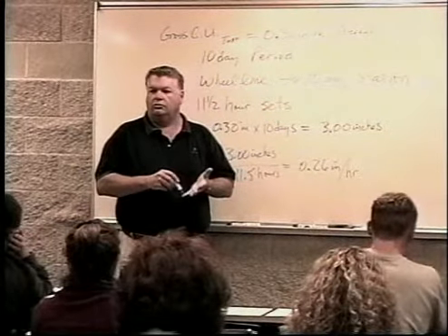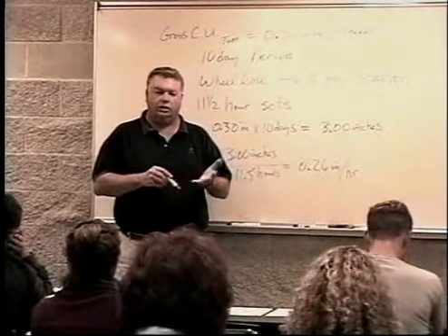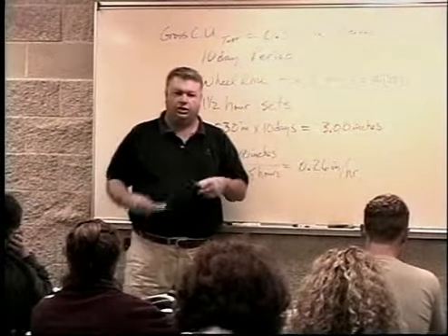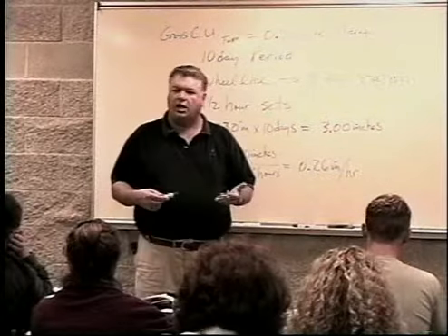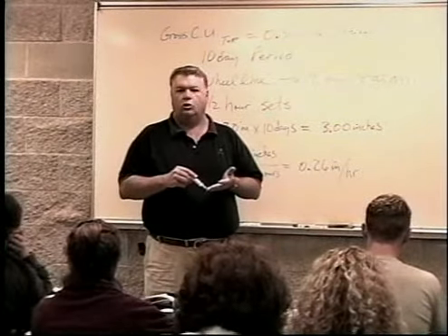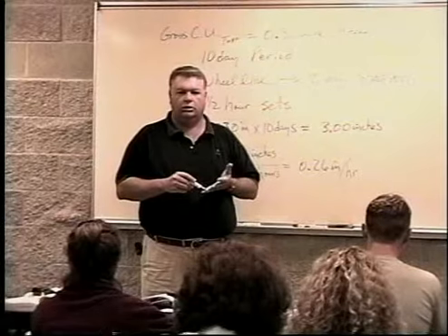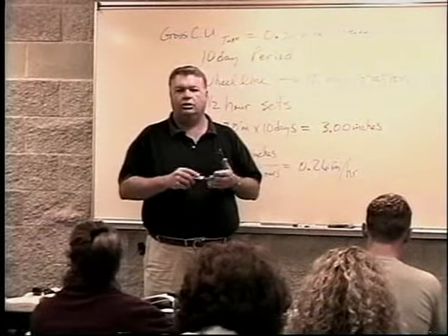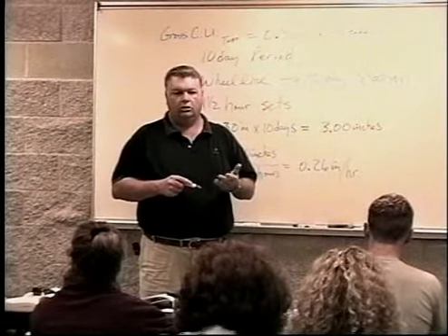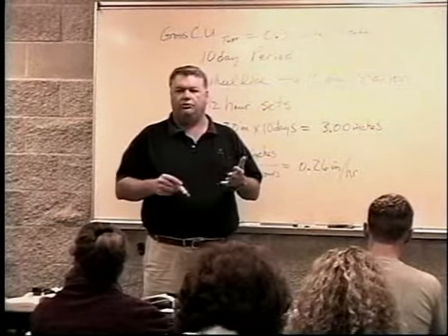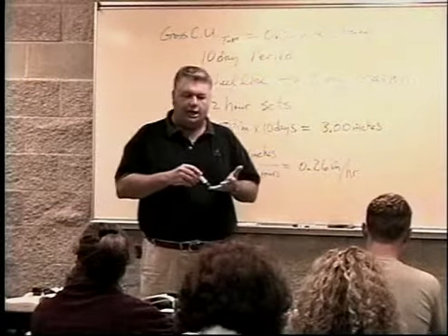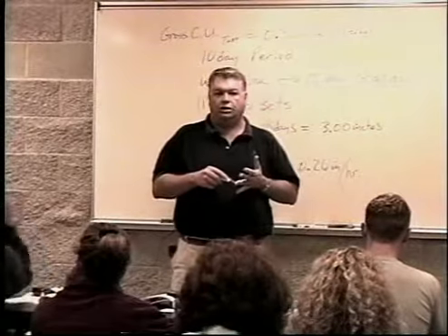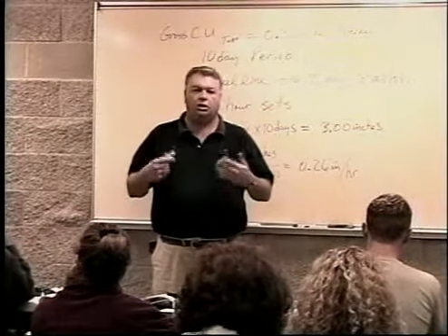The standard set changes for hand line or wheel line are 8 hours, 12 hours, and 24 hours. Because you have to be consistent on a daily basis. It's hard to go out at 3 o'clock in the morning to move the line. You can't see what you're doing. So you got to do it in daylight hours so that it works. And so what you do is you pick time frames that fit. And in the summertime, you can do 8-hour changes and it'll work. Some guys will even go to 6-hour changes if they're trying to pre-emerge new seeding.